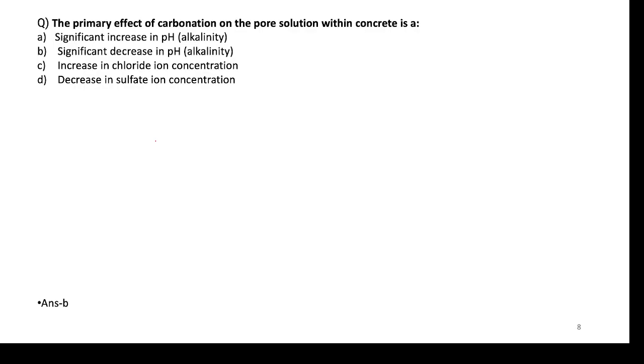consequence of carbonation, which leads to reduction in the pH, and the reduced pH can lead to decalcification of the passive film. Reduction in pH can initiate the corrosion of steel if there is steel reinforcement, and that's why carbonation is also important to study.